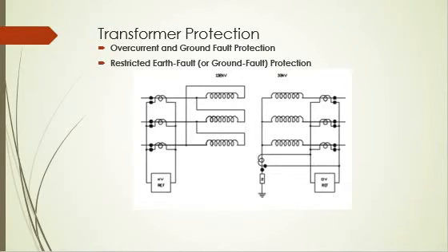For transformers of around 10 MVA and below, primary fuses are normally used. It is desirable to set the relays or fuses as sensitive as possible. However, they must not operate for any tolerable conditions such as magnetizing inrush, cold load pickup, or any emergency operating conditions.